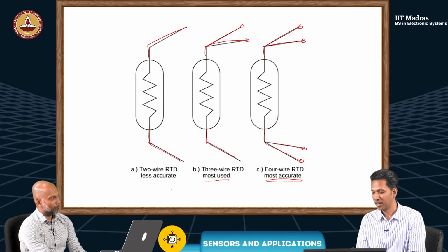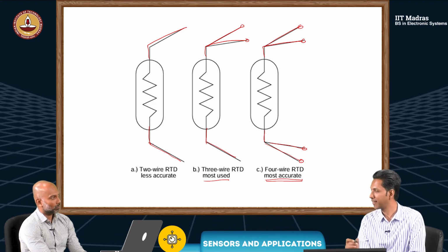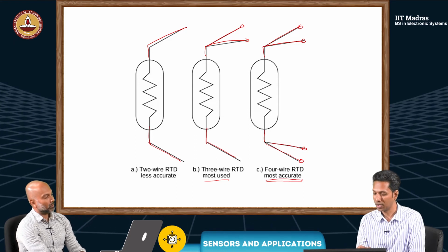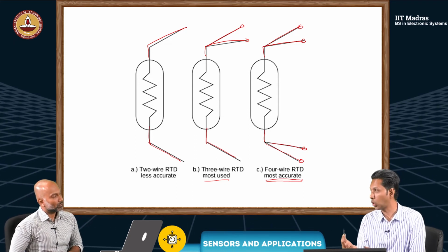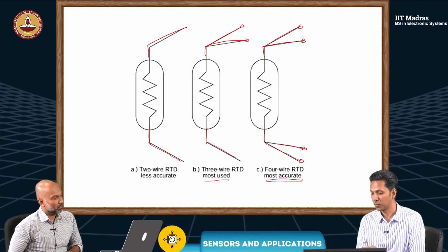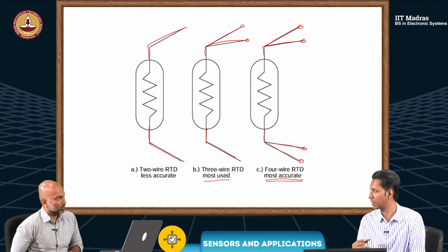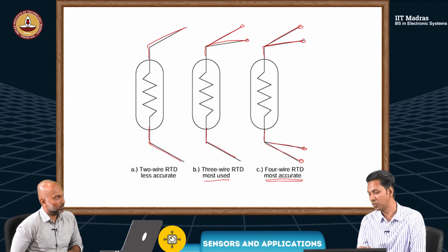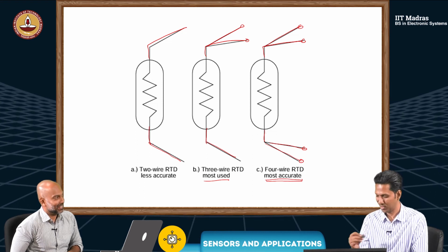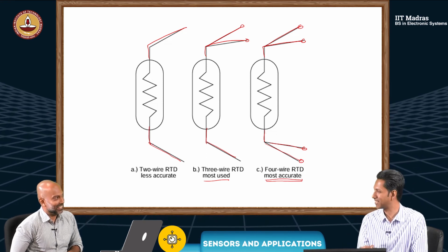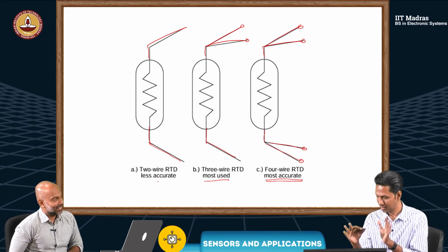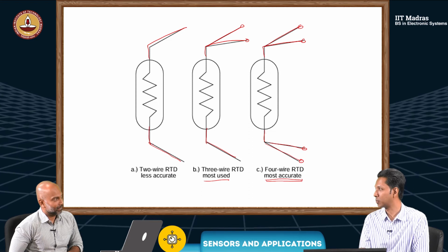In a bridge, this forms an additional leg or an additional terminal. It can solve the large offset error due to the RL1 and RL2, but there will be some gain error due to that. We will give this as an assignment, and maybe they should solve it by this, because this is most used. And it's just a small extension of the simple Wheatstone bridge.